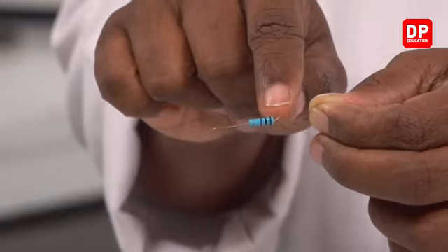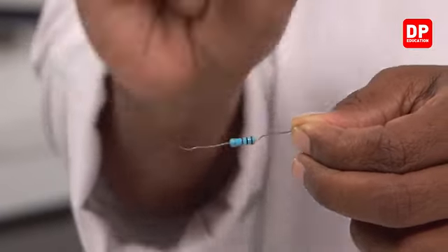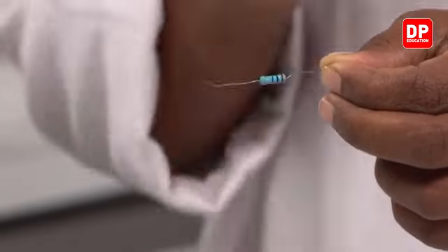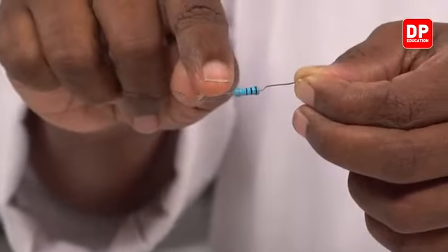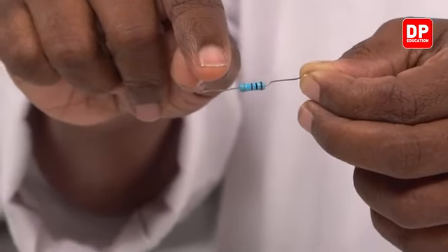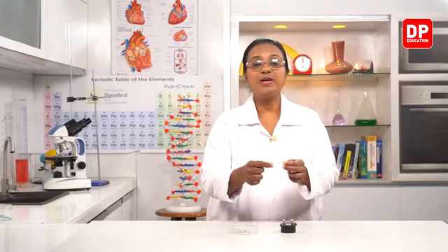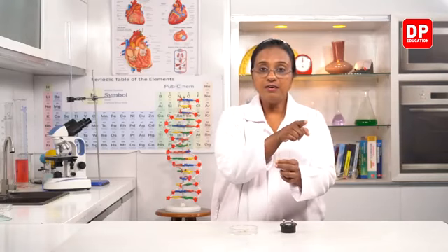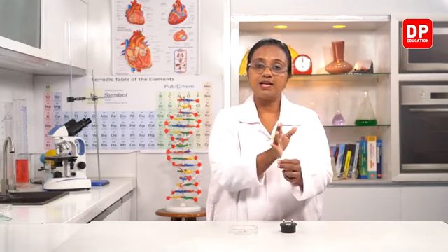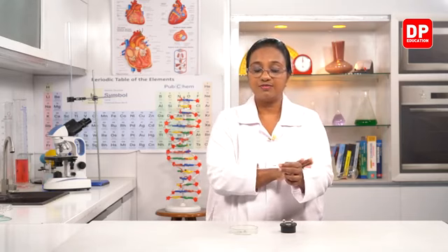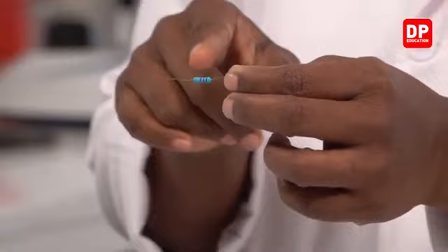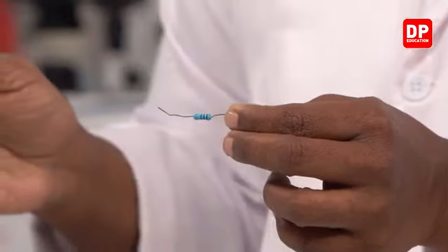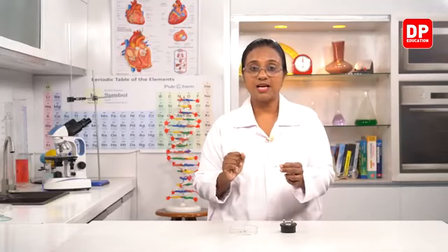In this, if you all look closely, there are four color bands. The first three color bands are somewhat close to each other, and on this side you can see the fourth color band. So always when you look at a resistor, you have to hold it in such a way that you read the first three color bands. The color bands that are close to each other are towards your left side. So they are the first three bands. And the fourth color band is the band that is away from the other three bands. That will be on the right hand side.